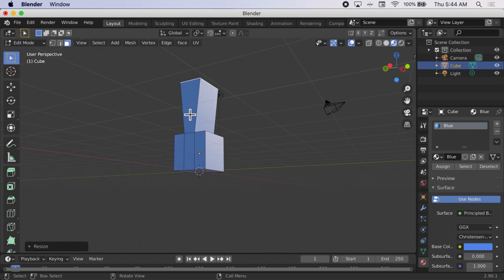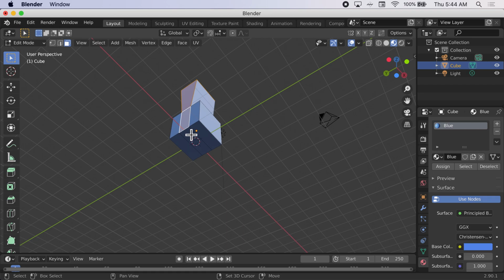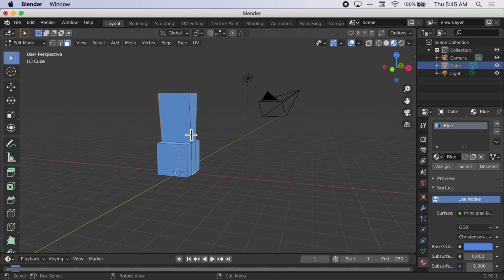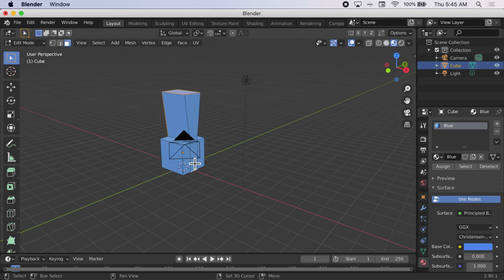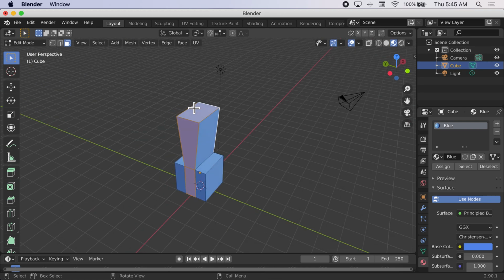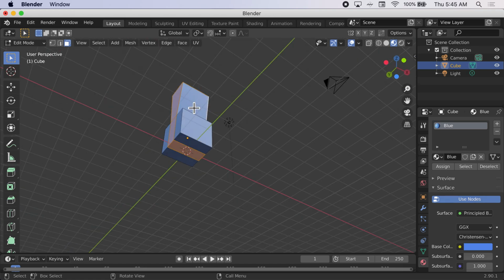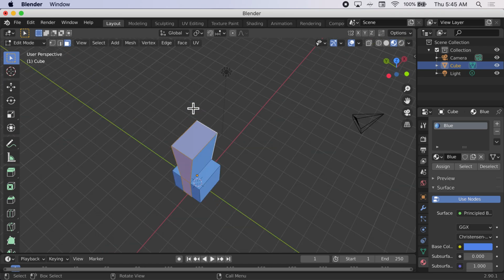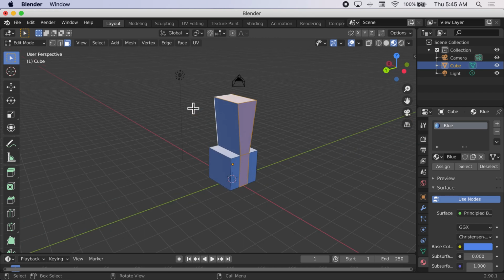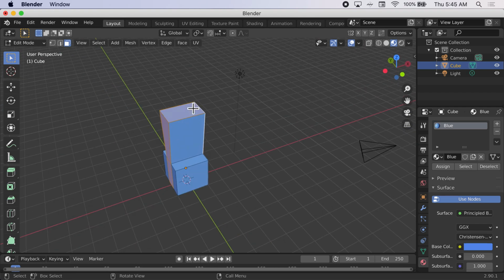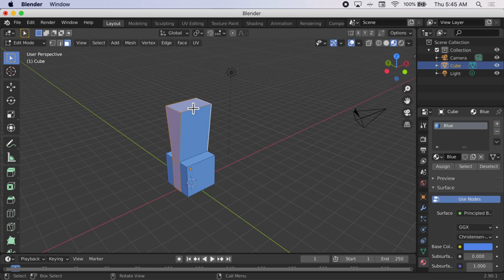The next thing we're going to do is we're going to go around with our 2 fingers on the trackpad. We're going to orbit a little bit, and then hold the shift key down and tap, and we're going to select more faces. So holding the shift key down as we go around, using our 2 fingers now to go around, as we select something, we're going to hold the shift key down so it keeps the other selections. What we want to do here is select all of the faces of this object going around the middle. So if you look what I've done here, and what you should do is go around and select all the faces along this middle line. You can think of it like a racing stripe or something.